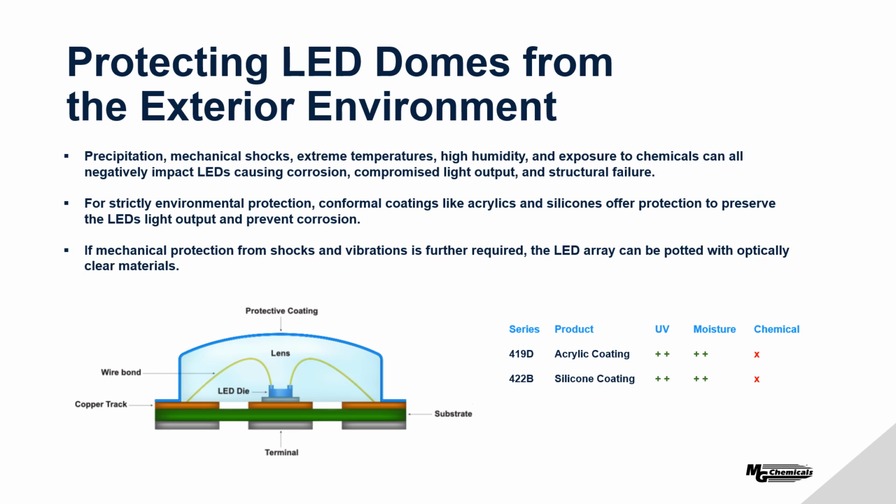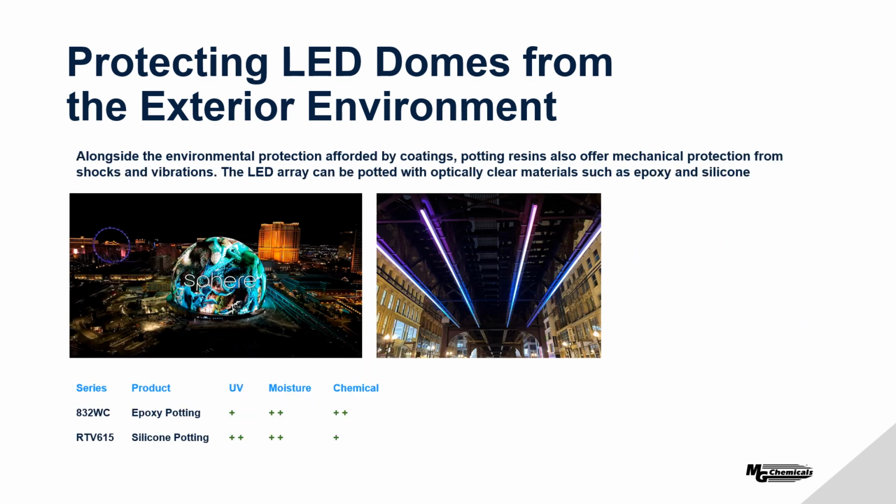So these are clear coats, and because of their polymer structure, these will not yellow over time. So they offer very good UV resistance, also very good moisture resistance. They do not, however, offer much in terms of chemical resistance. So if they were to be exposed to chemical solvents, fuel vapors, they would degrade very quickly, and it's not a viable option. So if that's the case, then we may want to consider instead a potting solution.